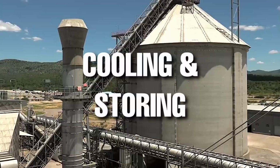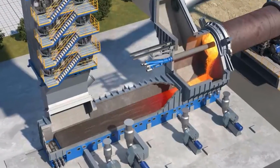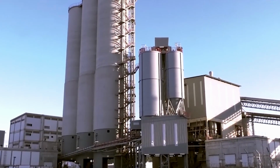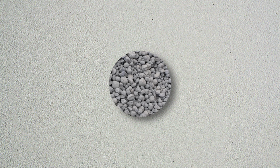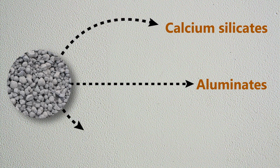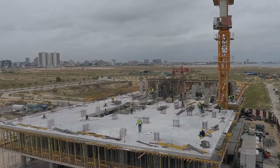Cooling and storing. From the kiln, the hot clinker is cooled using large quantities of air. The cooled clinker is then stored for further processing. The heating process in the kiln is essential for the transformation of the raw meal into cement clinker, which is the key intermediate product in cement manufacturing. These clinkers are small, marble-sized nodules that consist of calcium silicates, aluminates, and ferrites. These possess the necessary chemical properties to form hardened cement.